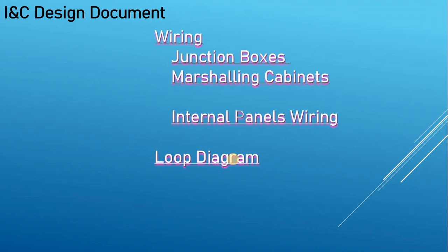However, for wiring, normally you get it from the database. Most of those databases can actually draw the wiring for you, and can give you the junction box details and the marshalling cabinet. So there is a lot of work here in preparation and in printing all those data. Sometimes each junction box will take a full day or 2 days. So part of it